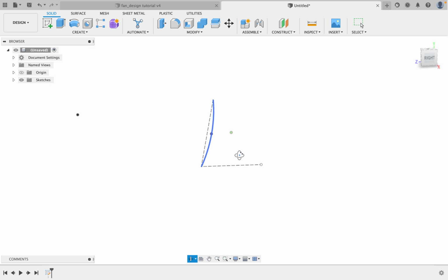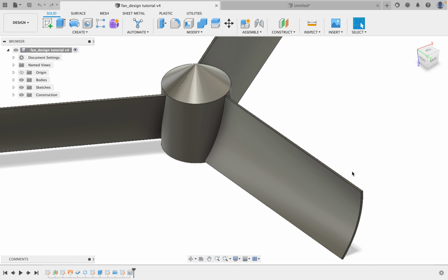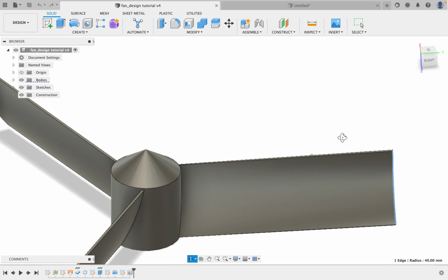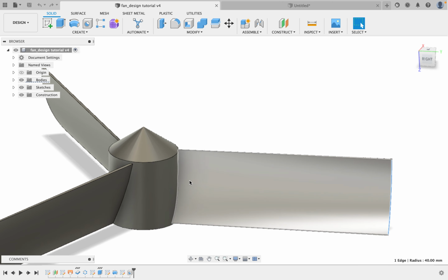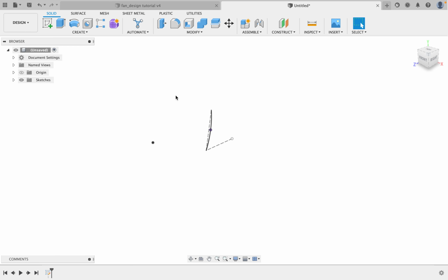So from there, I want to create a new offset plane so that we can define this edge of this arc right here. What we've just drawn is this one. Now I want to draw this other one here, offset by a particular distance. So we have this one here and this one here. There's a particular distance in between. The way to do that is, number one, we first need to identify what plane we sketched on.